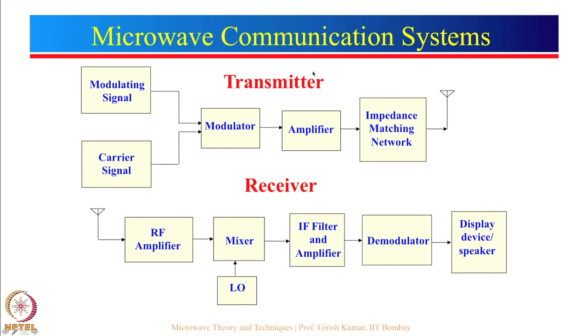In fact, many a times in the transmitter, mixer may be used for up conversion also, where the two frequencies may be added and get the sum of the two input frequencies. But over here majority of the time it is the difference of the two which is known as IF, intermediate frequency. So, again what we need now, IF filter and then amplifier.